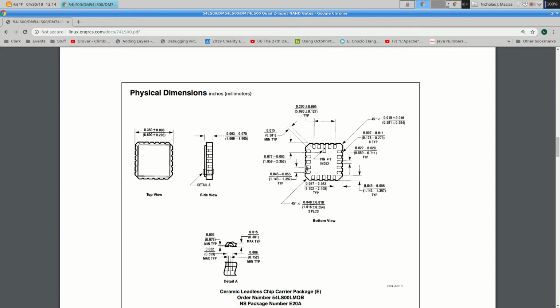And they're generally smaller, because if you have holes, you've got to have a certain amount of space between those holes. Otherwise, you don't have holes. You just have a big hole. So the surface mount, you can have these wires that are very, very thin and close to each other, and each of these will make a connection to one of those wires. And this is where you get really high density chips. So you might have 100 connections down here, and the whole thing might only be that big.